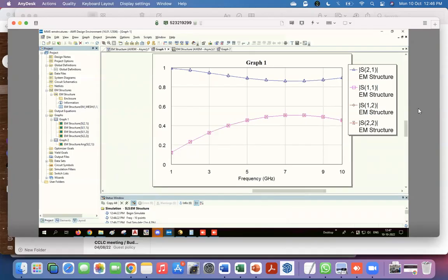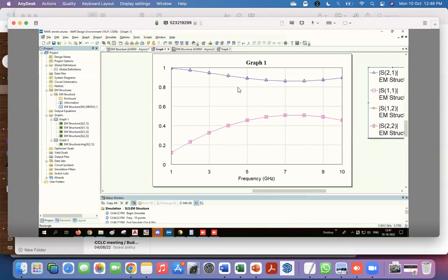So now this was a deliberately reduced transmission line, and now you are starting to see the effect of the reflections. You're getting this periodic behavior. If it was much longer, because we did not even have 180 degrees there, this thing would have repeated itself after that. Right? But if I make the transmission line longer, the simulation will take even longer.